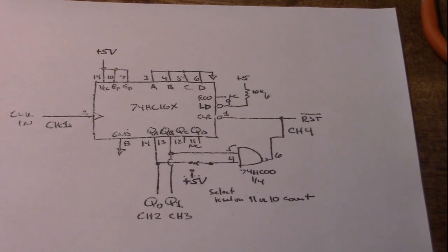Alternately, if we connect the NAND input on pin 4 that's normally connected to QA to 5 volts, the 74HC00 effectively becomes an inverter, and it inverts QB. So our count is going to be 0, 0, 0, 1, 1, 0, and on a count of 2, 1, 0, the output of the NAND gate will go low, asserting clear. And depending on whether it's a 161 or 163, the counter will either clear immediately or it will clear on the next rising edge of the clock.